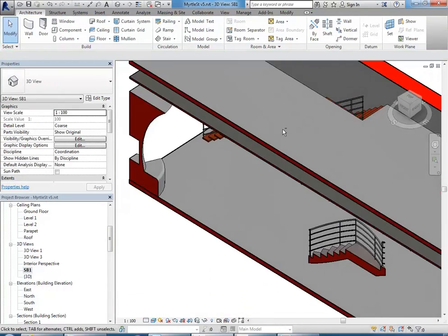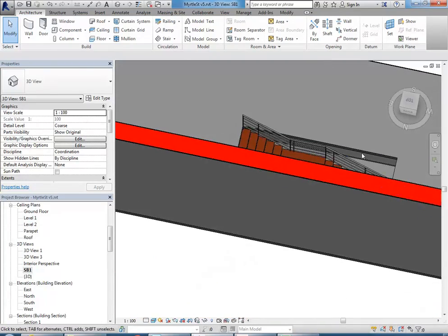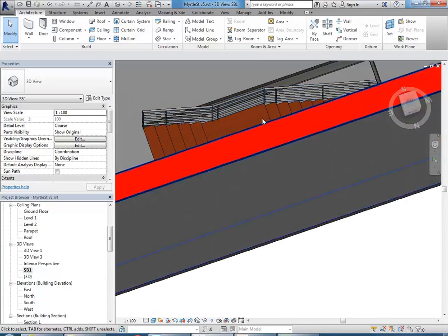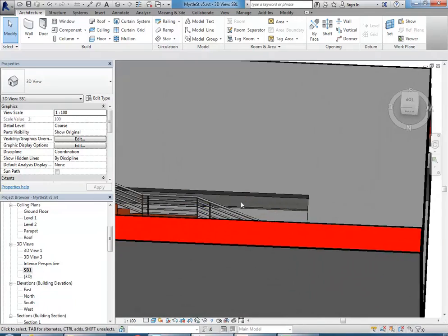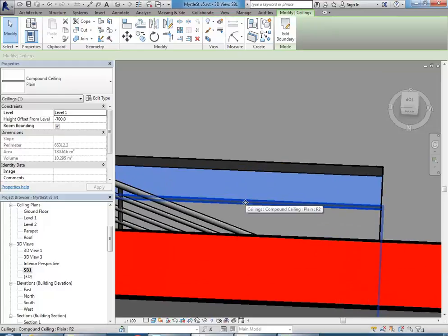But remember, if you're going to have an exposed section, well, it's really a fascia technically, between your ceiling and your floor there, which is pretty common around staircases, and it's a common problem you'll face in interior design, how to make that look good, or how to treat that at least, so you'll have some sort of material finish there, then you need to address that. And there are a couple of ways. Probably the easier way at first in Revit is just to make the ceiling really thick, so it fills in that space at least. Not the way you build it. The way you would build it is to have the ceiling just like that and then cover that section up with basically a big panel. So think about that anyway.